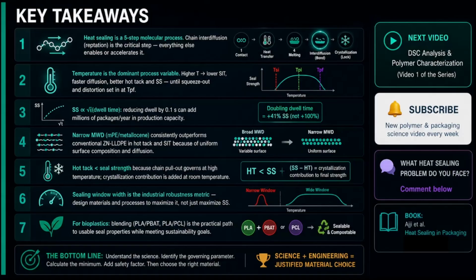2. Temperature is the dominant variable. It controls melting, diffusion rate, and sealing window. The seal initiation temperature is not an arbitrary spec. It reflects the melting point and molecular architecture of the sealant.